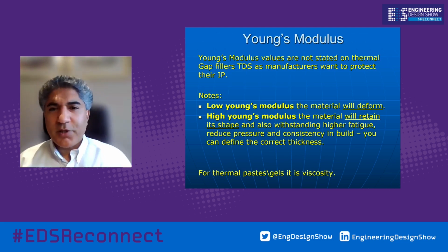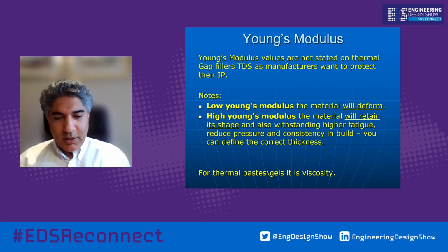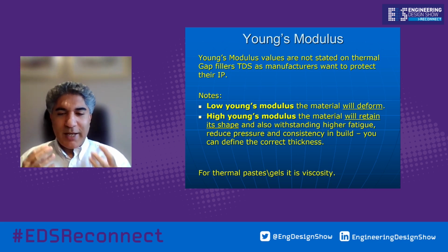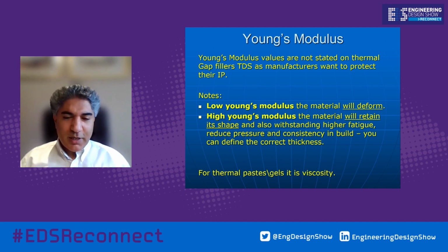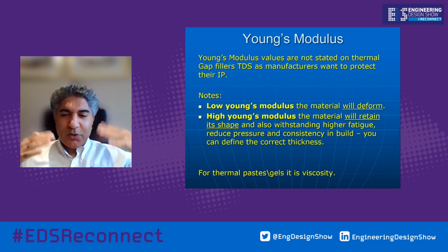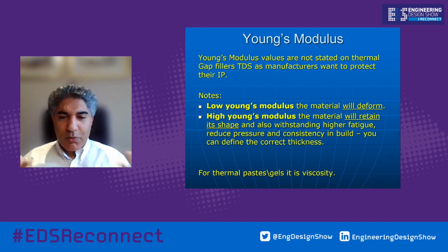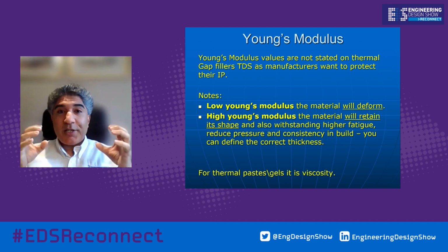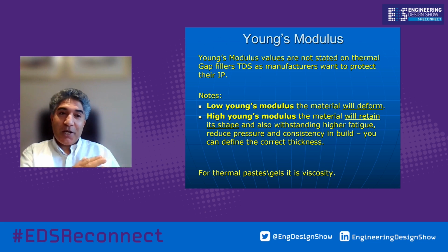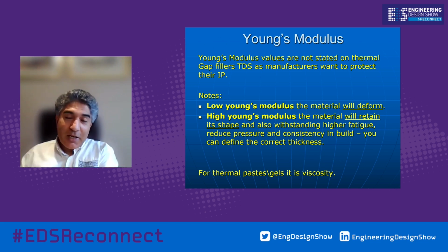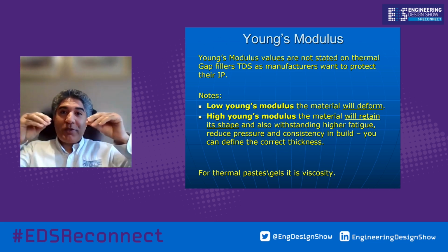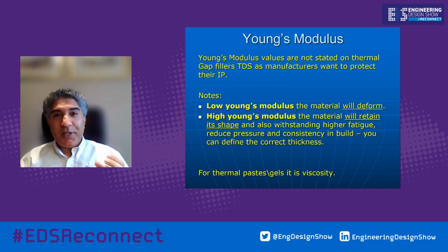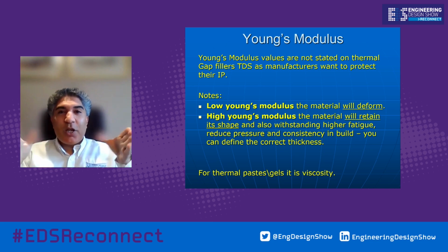Okay, so why the focus on Young's modulus? As I said a few seconds ago, you want to put less stress. You haven't got the ability to exert stresses, so you're concerned about the solder joint; exerting stresses could actually damage your component or a board. So low Young's modulus materials tend to continuously change. They're not going to keep a static shape. So yes, you'll handle your stress issues, but for longevity and reliability in the field, the material continuously oozes out or pumps out. However, if you design features, surface roughness or a cavity, you could mitigate those